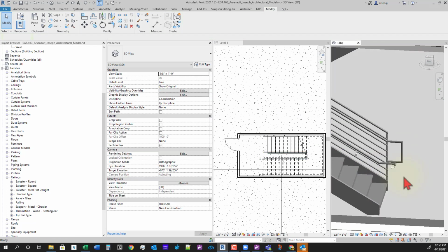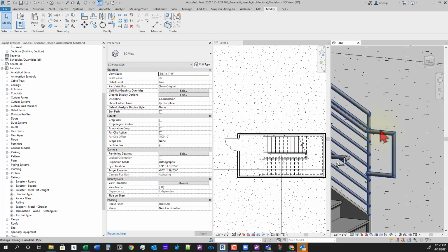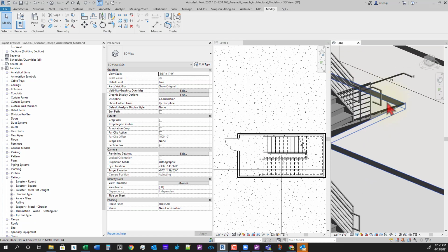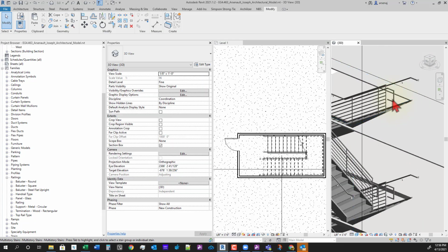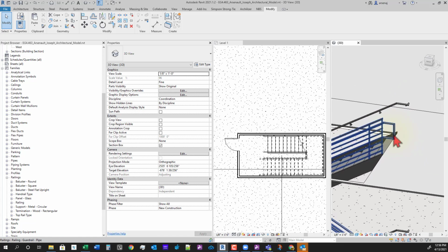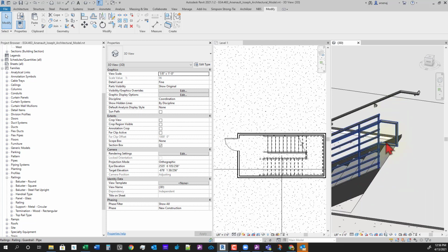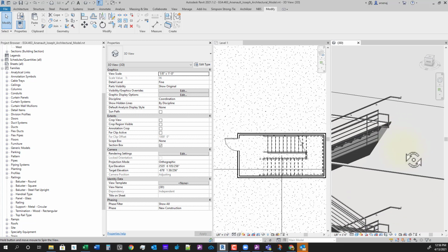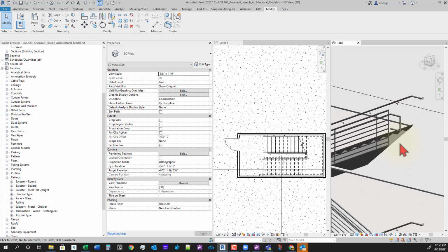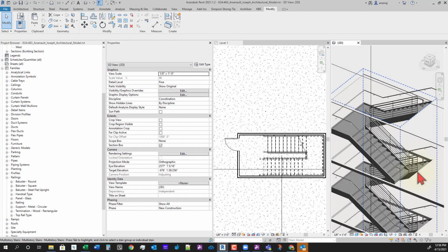You can see that it now curves back this way, so that we have this handrail extension on all the sides. By code, this has to extend out 12 inches, or in some instances, the code will say 12 inches plus the stair tread depth, which you could see as an option when we were in there. And so here we have the guardrail, we have our stair.